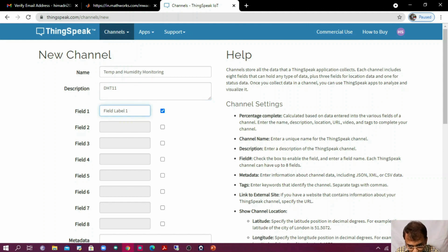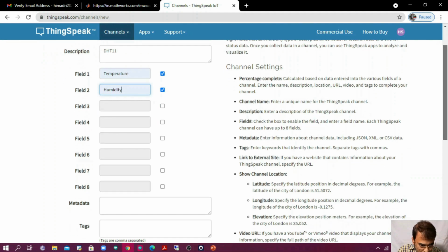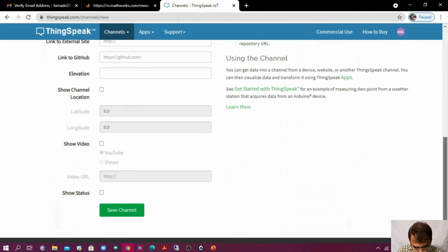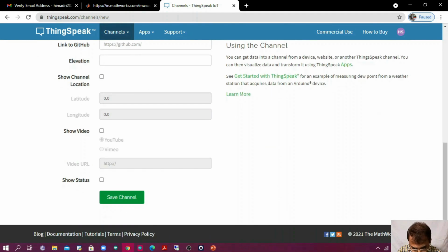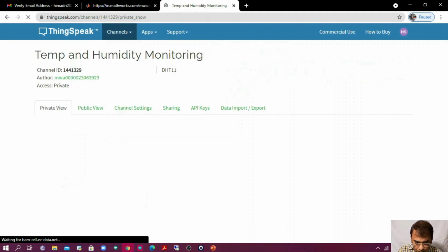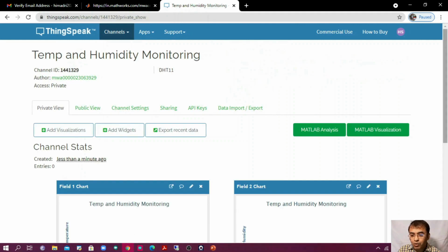So now you select the field. In our case, the first field is the temperature, the second field is the humidity. Select this one. Next is humidity. Okay. So now just go down and then click on save channel. As soon as you click on save channel, you will get this channel dashboard.